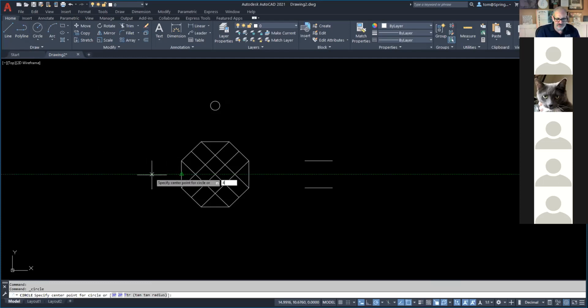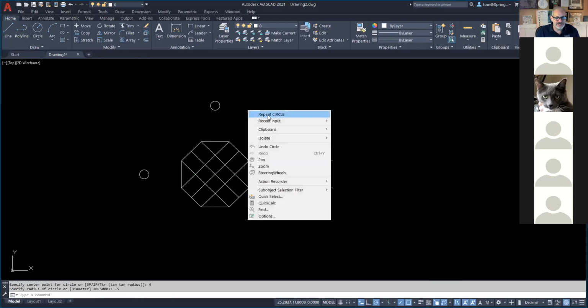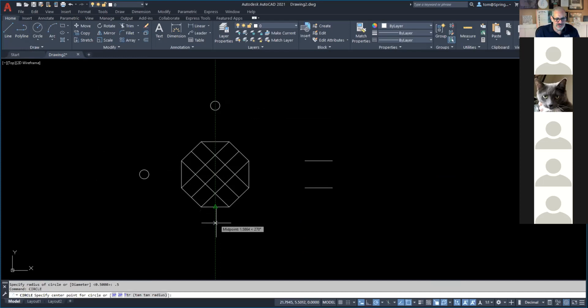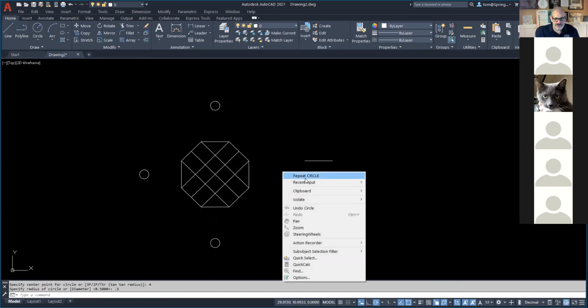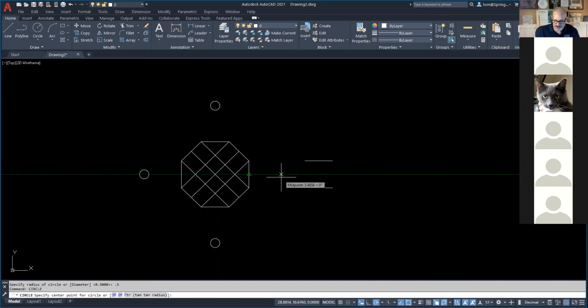So I'm going to go over here. I think I said, what did I say, 4? Yeah. And I'll say 0.5 like that. And this is what allows me to now put this together here by just touching it and pulling it down here. And this is how you could actually begin to put in content in AutoCAD with a lot of precision. So these are some tools that you have right there. So that's object snap tracking. It's using object snaps and it tracks using them.